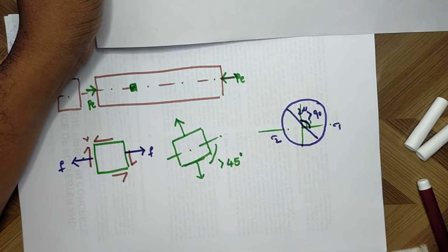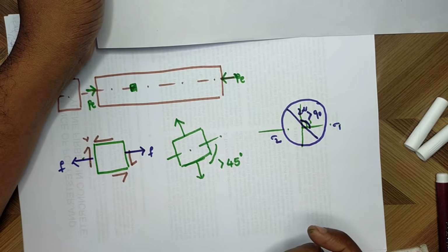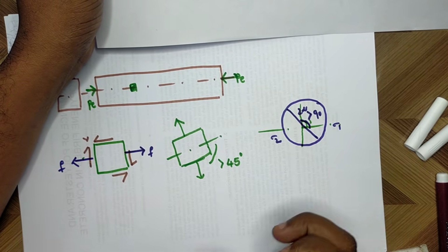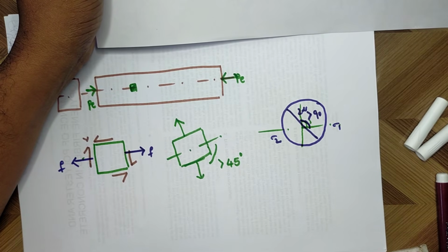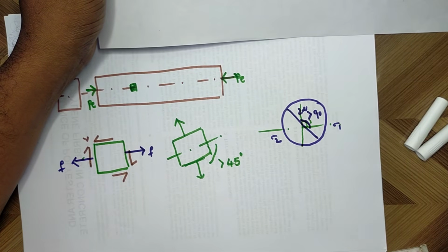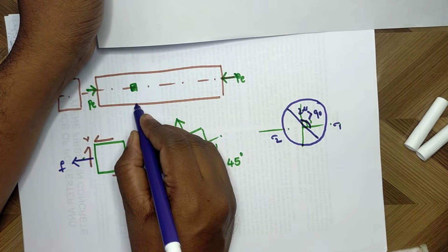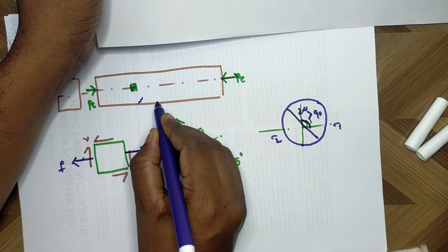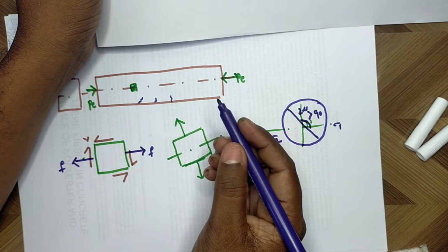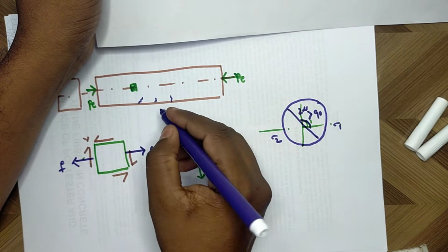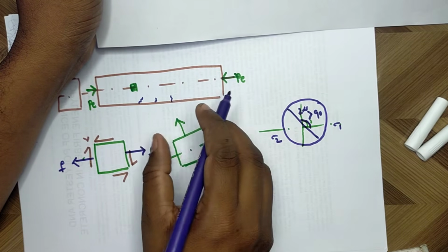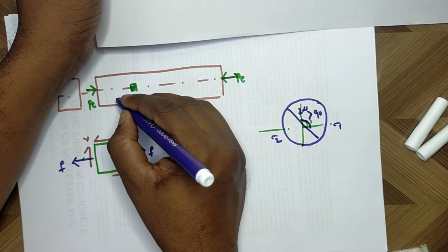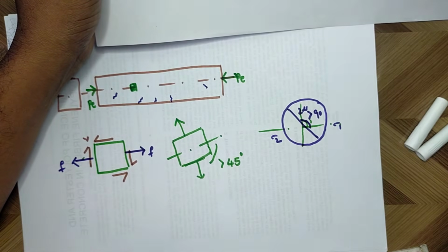See, the formation of cracks for a prestressed beam with large span to depth ratio and uniformly distributed load will be less compared to RCC. Obviously, in this case the cracks will develop, but they may not propagate much. They may not propagate, either flexural cracks or shear cracks.